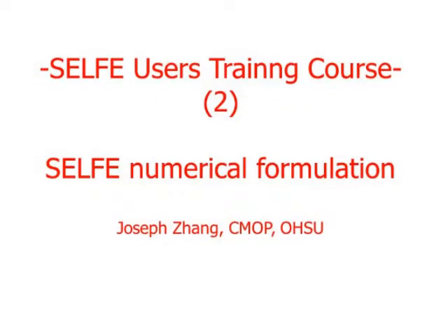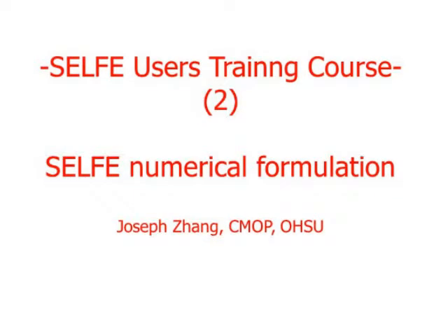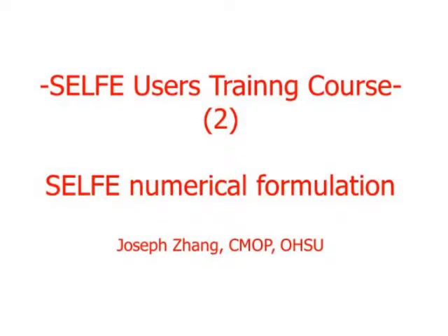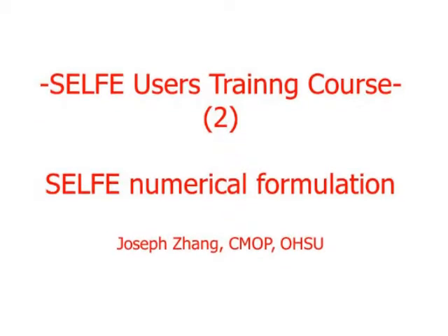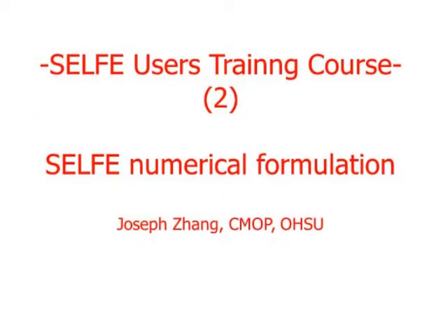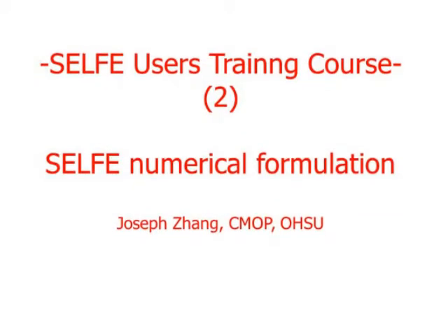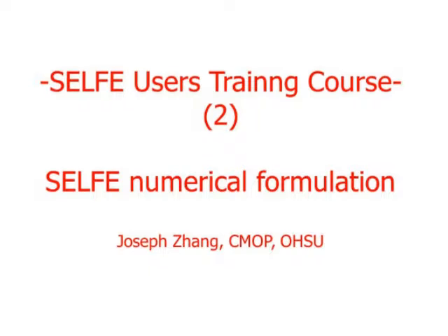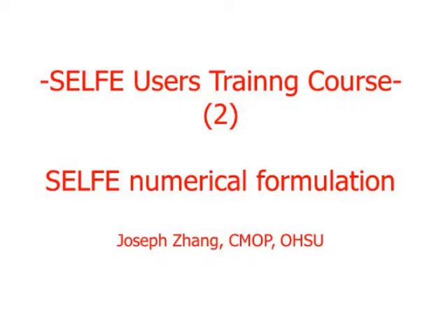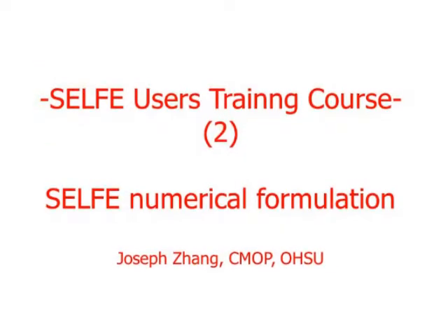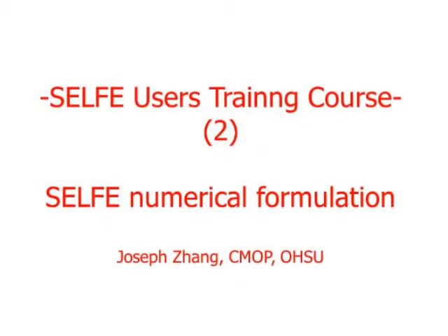So next, slide number 13. Let's look at each individual term in detail. I1 is the only one that really has the unknown elevations. If you use the linear hat shape function, then you can discretize them and express them in this form, summations. Delta again is a canonical delta, and I prime is basically a position in a particular node. And L is basically a dummy variable here, so it also denotes a particular node, if you think that way.